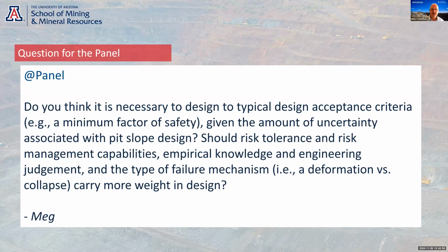And I guess the challenge here is, what is a typical design acceptance criteria versus what is your design acceptance criteria? And when identifying that pass mark, whether it be a factor of safety or a strength reduction factor or a probability of failure, all those things you mentioned, risk tolerance, empirical knowledge, engineering, type of failure, confidence in your geological models, your hydro models, all have to come to play to basically be part of that design acceptance value that you choose.